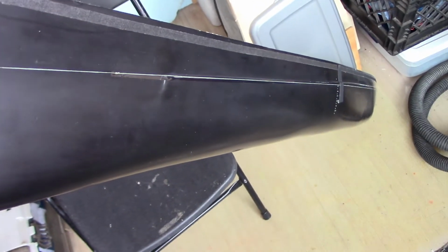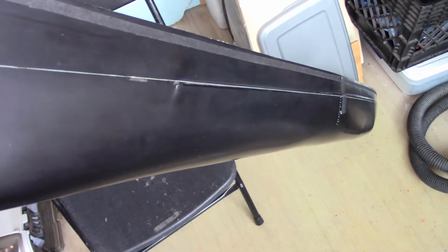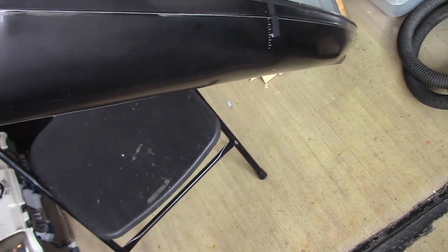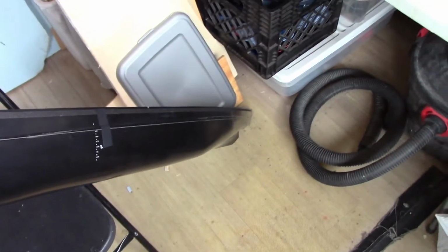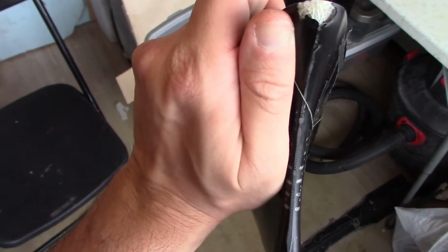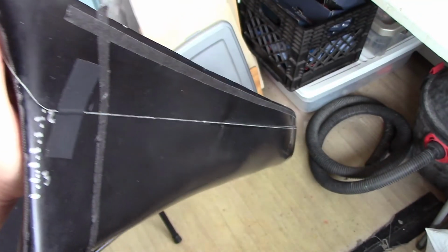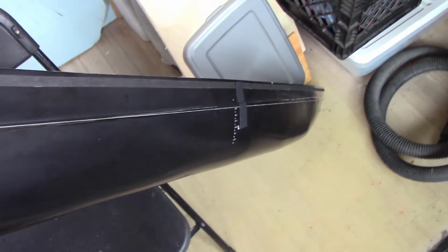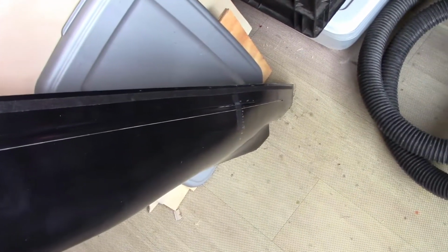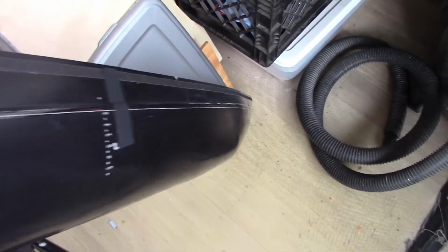So I marked the waterline at the one that gave me just about 1 inch and 1/8, and then those marks ended up being 1 7/8 in the bow, 1 3/16 bow forward, 1 1/8 bow aft, and then just about 7/8 in the stern. And you can see I put a string here and I taped it at the various markers. And then what I do is I look down the hull and make sure that there's no really bad kinks in it. When I first did it in the stern, it kinked up a bit. So you can see it's pretty straight, which is good. If there's a kink, that would mean some of my readings were wrong.